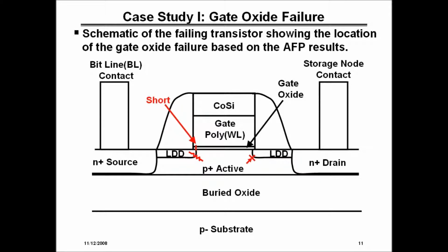With aluminum metallization, you typically also have tungsten vias, and so in that case, unlike on copper where we wanted to probe on the metal lines, on the older aluminum metallization technologies we want to probe on the via plugs because they are tungsten and easier to probe. But yeah, we have probed on aluminum metallization, and it works.